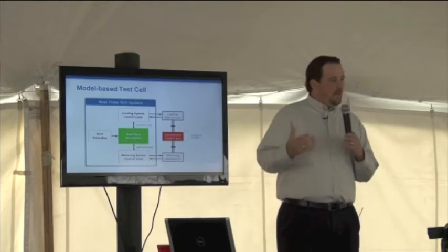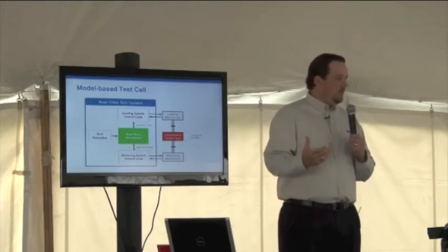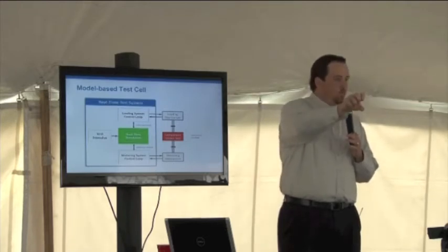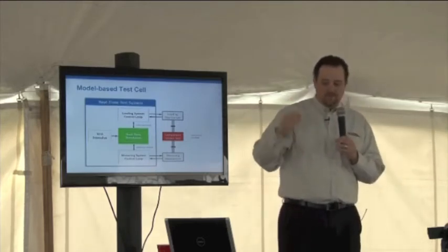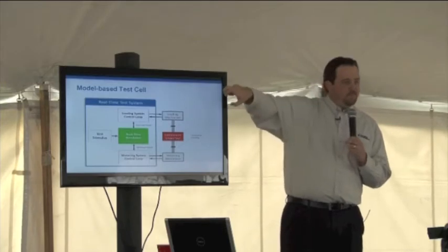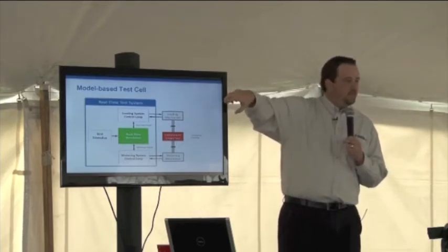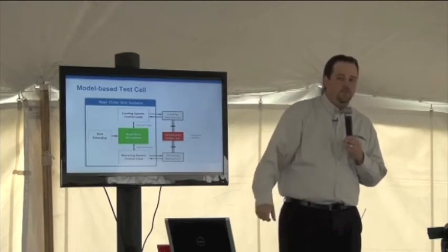And so all of that can be calculated in real time, so you have this simulated vehicle, but you can take that simulation and pluck out one of the models, the model of the differential in this example, and now put it physically into the real world and have it think that it is actually inside of the actual vehicle that you have specified.